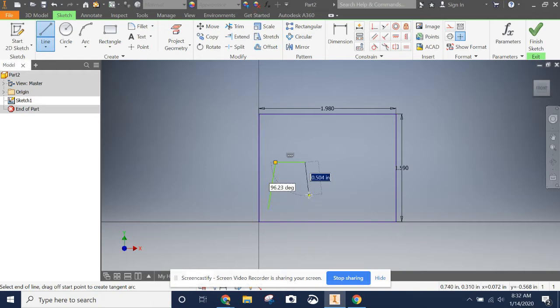If you see down here at the very bottom, coming out of the left side of my cursor, those dotted lines that are lining up with the bottom of the other line, that means that we are in line with that. So that's a collinear constraint that we're getting there. So now we can make sure we're going horizontal, directly vertical, directly horizontal, vertical in the down direction, once again lining up with everything, and then finally closing off the shape. You can see that the shape's closed off because of that green dot. Now we're going to hit escape. So we have the A shape.